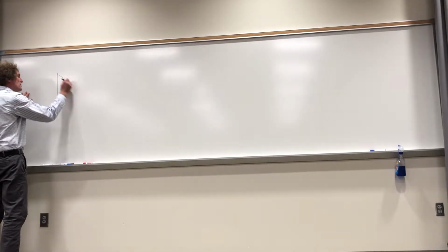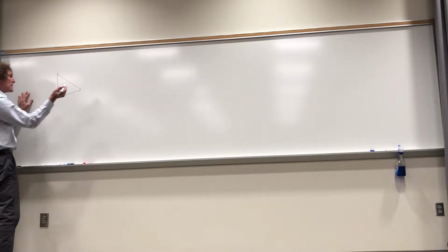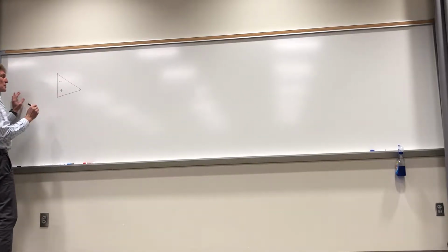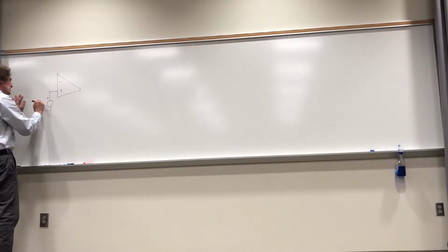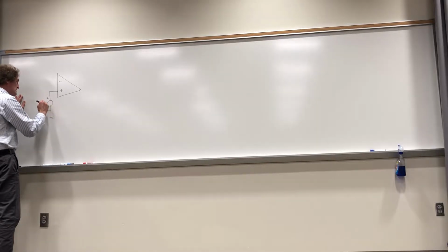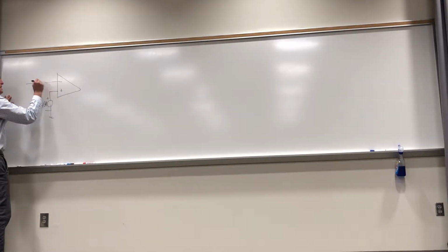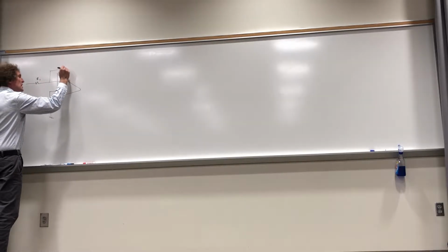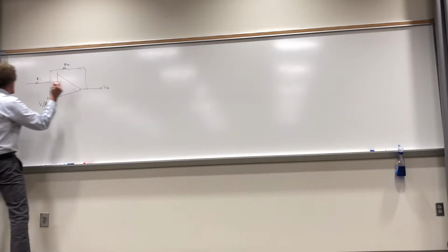If you have an operational amplifier as such, you don't know what it consists of and why certain things are the way they are. That's the negative, that's the positive terminal. Now you can feed the positive terminal right there with a voltage, call it Vin of t. That's allowable, and it's done. As a matter of fact, who came to me with that op-amp design last class? See me after class, I can help you with that, if you want. I'll show you this. Then you're going to have some R1 here, and some R2 here. This will be V out, and this is going to be grounded.